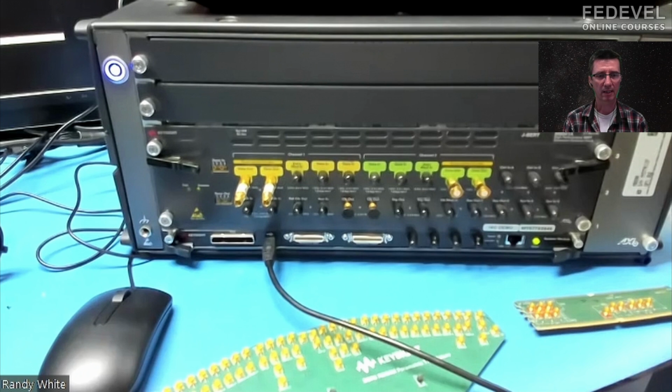Okay. And this kind of system can measure DDR5, 4, 3, all the kind of memories? Yeah, it can support the slower speeds, but only DDR5 is the only generation that actually requires receiver tests. So for a DRAM manufacturer to offer the memory, they have to prove that they've passed these tests, and usually they're in the data sheet. Here's the BER data, or here's the way that we train to get the optimum receiver equalization.